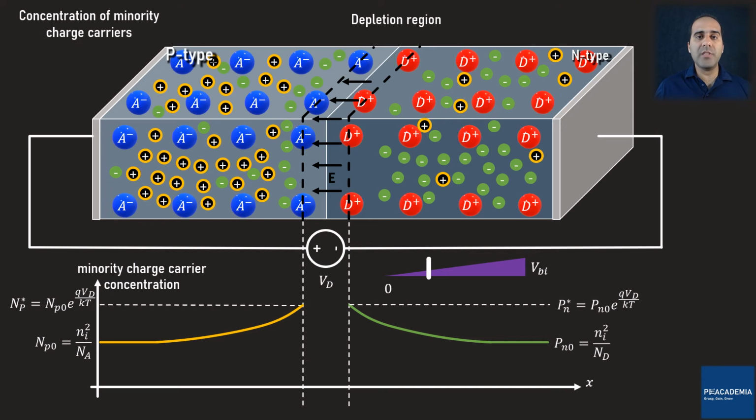Once the free electrons diffuse and arrive at the P semiconductor, they recombine with the majority charge carriers, holes, in the P semiconductor. However, due to thermal excitation, generation happens, and due to the external electrical field of the positive metallic contact, electrons move toward the left and are finally absorbed by the positive metallic contact. The free electrons are now in the conductive wire. They go to the voltage source, and from the other side, they enter the device.